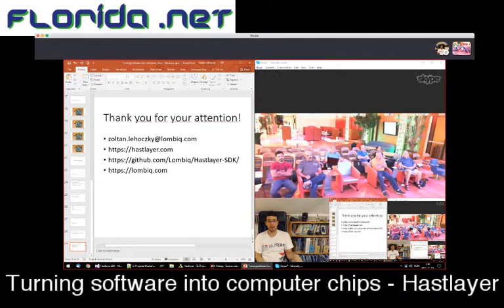But ASICs are, just as in the example of Bitcoin mining, feasible if you want the maximum performance and power efficiency, and secondly, if you can sell tens of thousands of units. Because if that is the case, then the millions of dollars of investment will be returned, and after you are manufacturing your ASIC, it will be cheaper to manufacture per piece than having an FPGA configured.